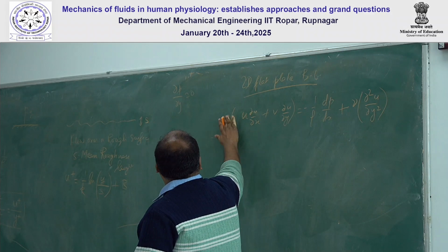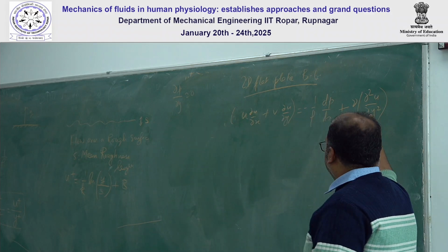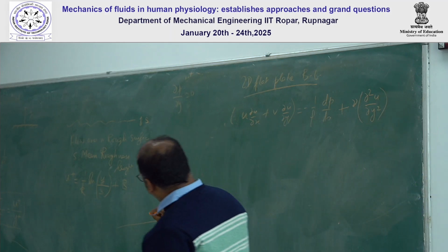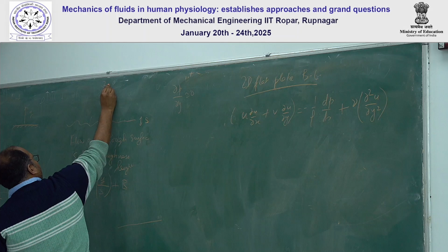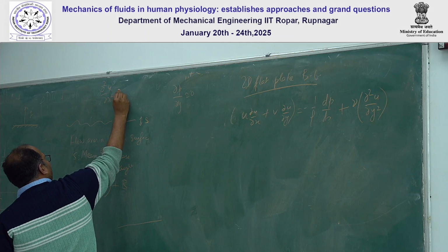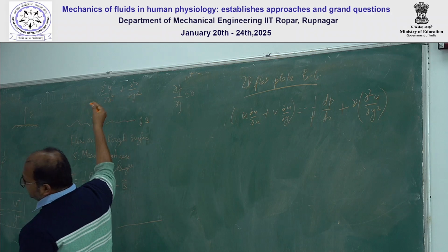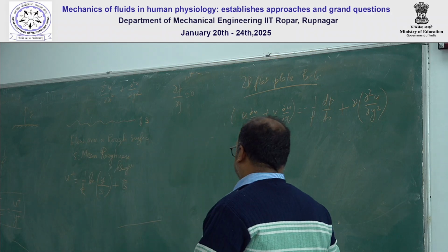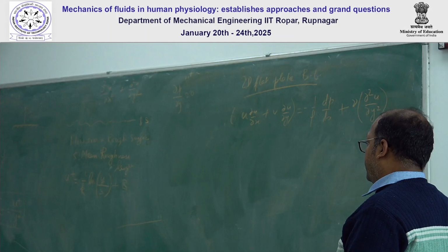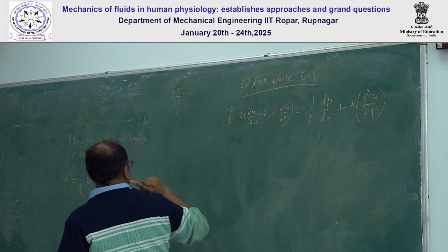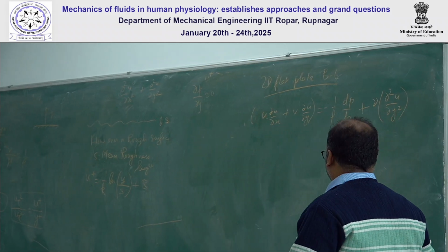Sorry. Yes, here again, using order of magnitude analysis, we start with the viscous terms del square u del x square plus del square u del y square, and then we show that the second order derivative with respect to y is much higher than the other term. We drop this term and keep only this term.